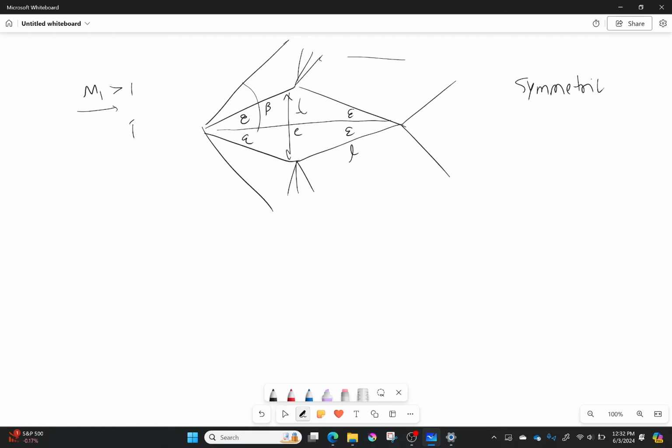And we can also figure out a few values. First off, if I have P1 right here, after I go through a shock wave, P2 right here is going to be more than P1. We know that because we went through a shock wave. Behind that, I will have an expansion fan, so P3 is going to be less than P2 because that expansion fan decreased it. What happens in section 4 after that last oblique shock? Who cares? It's not attached to our airfoil. So we really don't need to know anything about it.